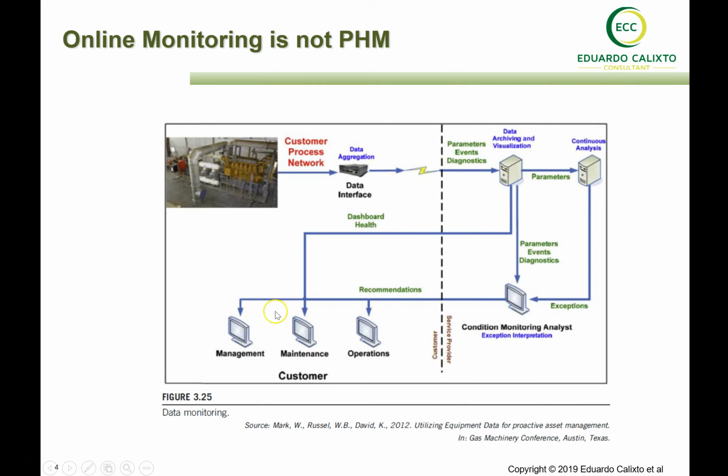Usually the maintenance engineers assess this information, and whenever some information shows that the equipment reached the top of vibration that can trigger a failure, they need to assess by themselves if it's critical for the equipment, for example the state of health of the equipment when it reaches such a target, and the remaining life.